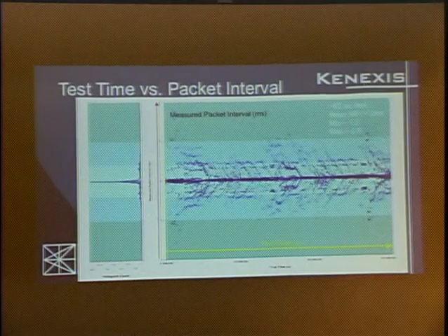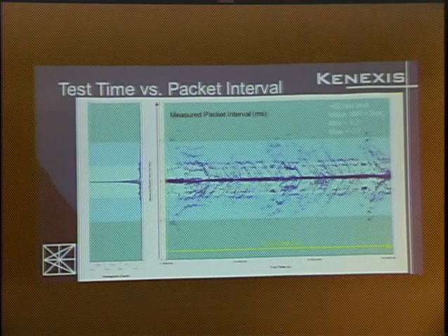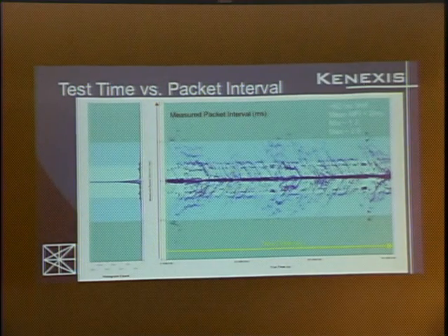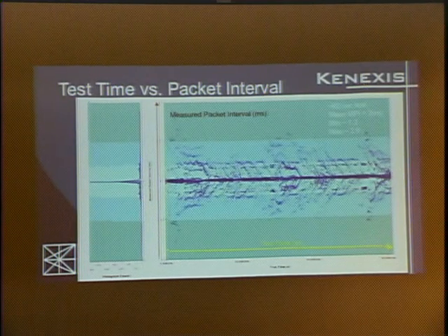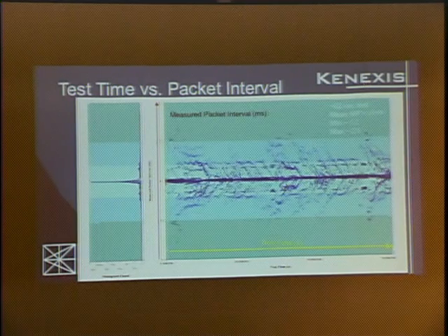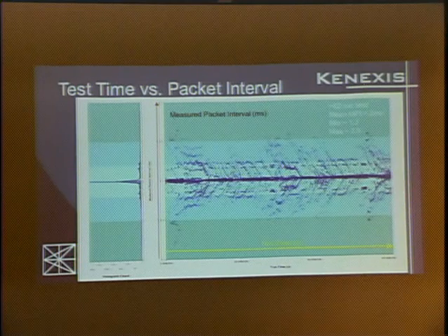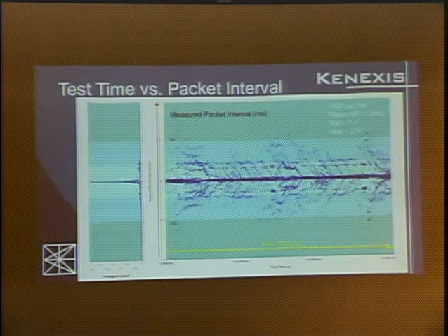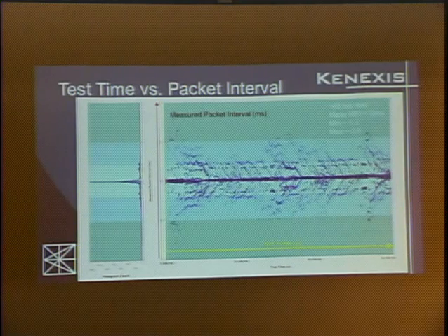That's 2 milliseconds right there. So we were supposed to be getting 500 hertz of data from this system, and you have everything from 1.2 milliseconds to 2.9 milliseconds. The communication protocols assume that TCP is not going to deliver the messages. So they make the assumption that unless you get packets that are really late, they're not going to try and shut down the communications. They're just going to assume it's really late and something went wrong.